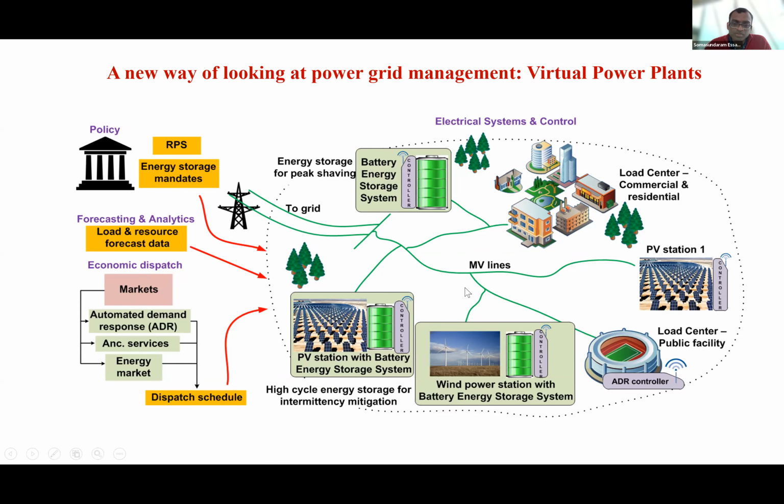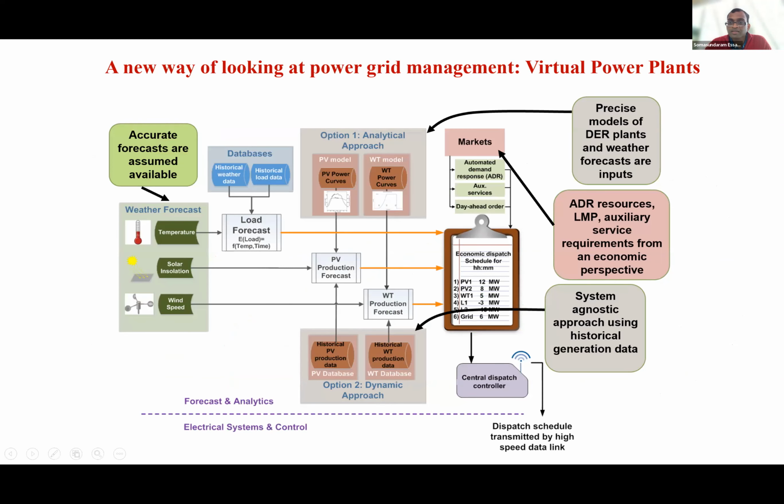So once that happens, like I said, at the future time, the stations generate that much power, and then we are all fully balanced. And like I said, if there is no balance between the generation and the demand, you're going to have an unstable condition. Best case scenario, the quality of the power goes down, and worst case scenario, you could have a blackout, right? So if I zoom into it further, you can see where all the power electronics and all the algorithms exist. So this just zooms into the two different areas.